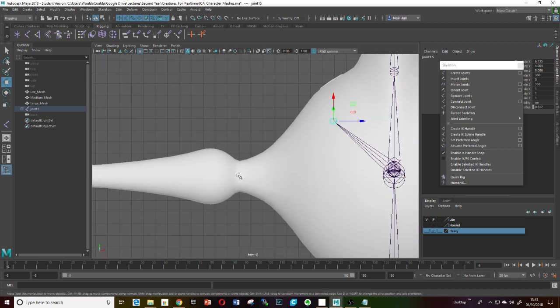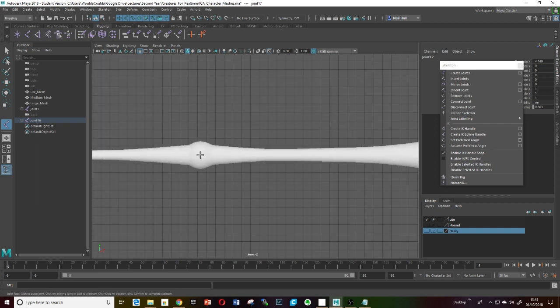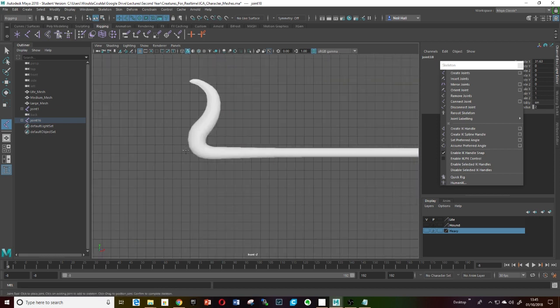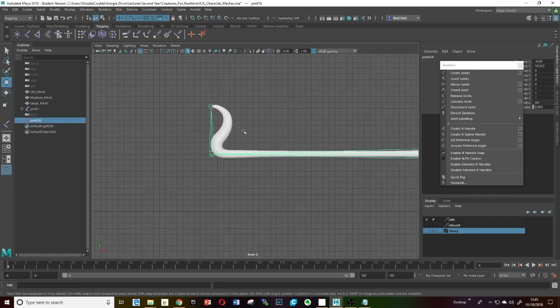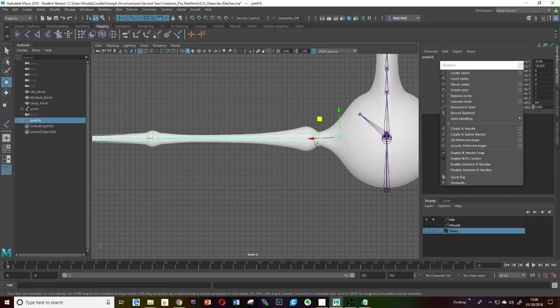If you wanted to, we could go straight in just to create a bone here straight away, but it might be nice to get some kind of subtle movement on this part of the bone here. So if we select the joint, perhaps somewhere around there, and then to the middle of the joint. If we work our way along in the joint there, a bit further along again, so perhaps to about there, and then along to the toe with a right click there. So we have our symbol set up there.